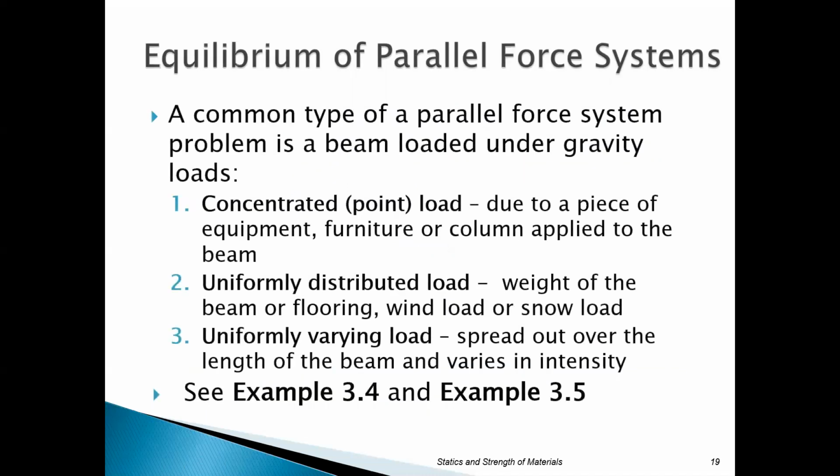So you do have to be aware of these types of things that can happen in your loading scheme. Typically we talk about either a concentrated load, also referred to as a point load, and then we have what's called a uniformly distributed load. Then you have what's called the uniformly varying load. The concentrated load is easy to handle, because it is what it is. But with a uniformly distributed load or the uniformly varying load, we need to get rid of that. We need to remodel it.